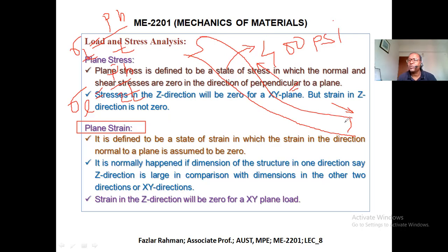For example, if you blow air into a balloon with your mouth, the radius will increase due to tangential stress, and the length will increase due to longitudinal stress. Similarly in the pipe, there will be some elongation. But compared to the length, that elongation is negligible.